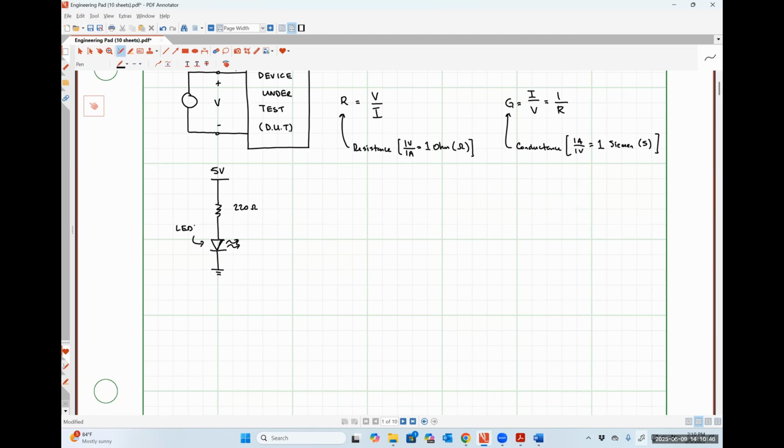And the larger the resistor you put in series with the LED, the dimmer the light that was emitted by the LED became. So much so that if you put a 10 kilo ohm resistor in series with your LED, which some students accidentally did, it was hard to tell whether or not the LED was even on because the light it was emitting was so dim. Typically, we used 220 ohm or 470 ohm resistors for bright LEDs, somewhere in the ballpark of a 1K for relatively dim, and anything larger than that, it was hard to see the light coming off of it at all.